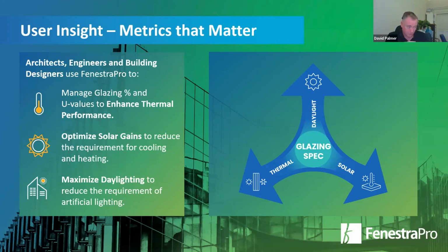Major components is not only glass specification, as it says in the slide there, but it's also the configuration of your glazing. So things like percentage glazing, distribution of glazing, configuration of your glazing arrangement, and of course the specification, where you can manage a lot of that with solar control glass in terms of minimizing your overheating, but also improving your thermal performance with better performing thermal glazing.